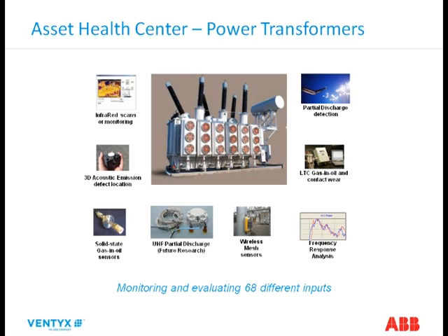But looking at the standard oil test, looking at dissolved gases in the oil, also utilizing partial discharge to detect any breakdowns of insulation. Also, we can look at bushings in terms of partial discharge. Frequency response analysis, looking at the inductance and capacitance of the windings to make sure there isn't any damage or if they have moved either because of a through fault or possibly from transportation. So we can integrate all of those different sensors and capabilities into the process.